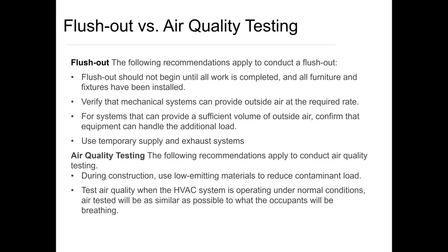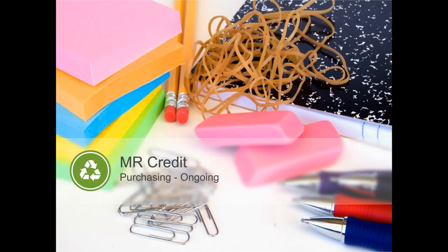So it's operating as it would on a typical day. The air is tested as similarly as possible to what the occupants will be breathing. There are certain contaminants that are tested for this air quality testing, and you have to verify that the contaminant levels are below the thresholds that are identified for LEED.